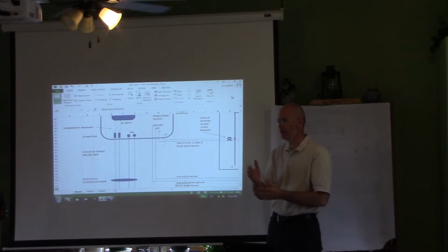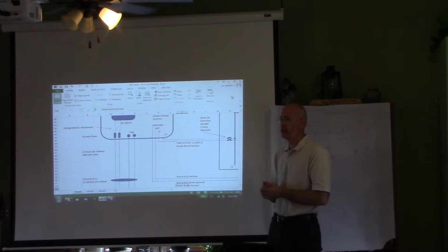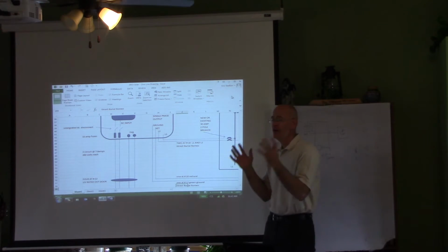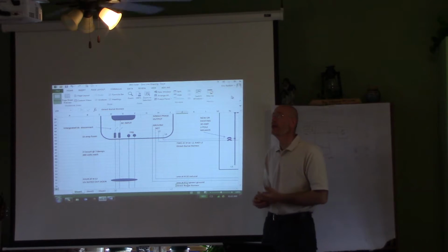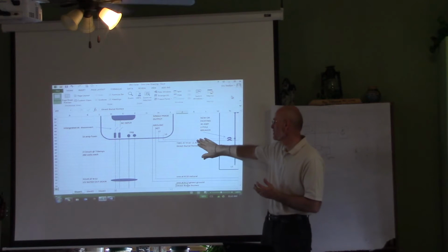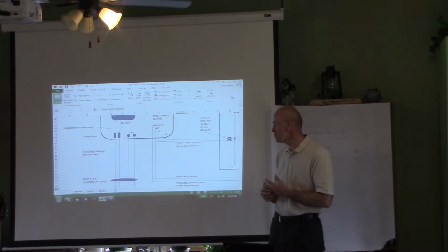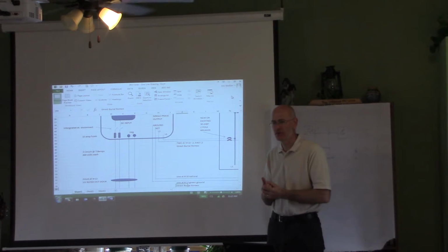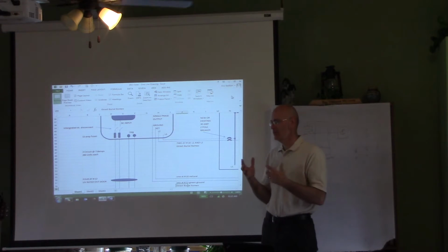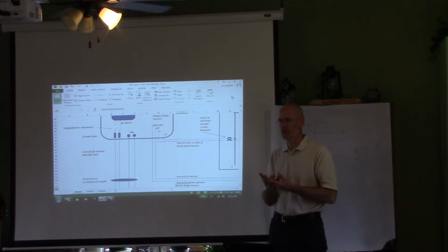I live on a farm and we actually had that happen where I didn't put my Romex in a conduit, and 4 years later it's like making static. I'm standing next to it, I'm hearing it, going, what is going on? Found it, I'm like, oh boy, I didn't do that right. So, you gotta use the right material for the right application. And that's where Eric's got experience in building things, and you don't wanna take shortcuts where nature and the environment are gonna degrade your equipment so it's not safe.